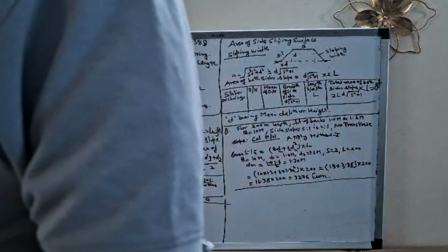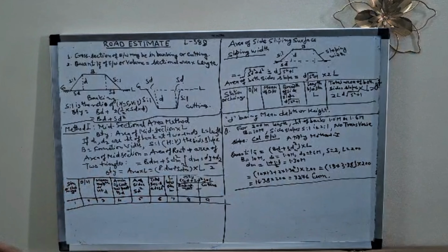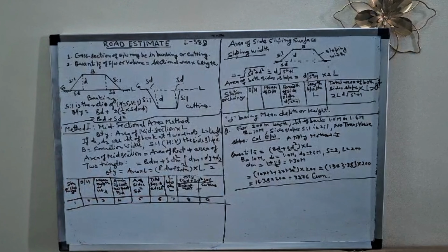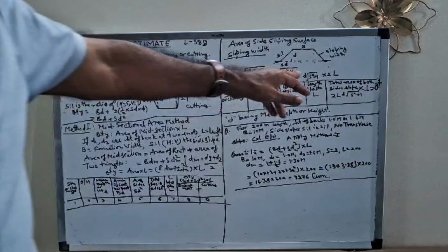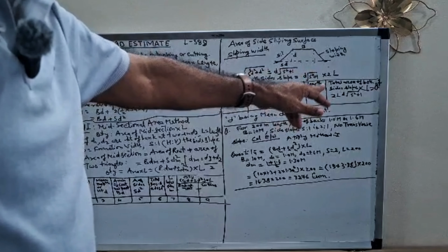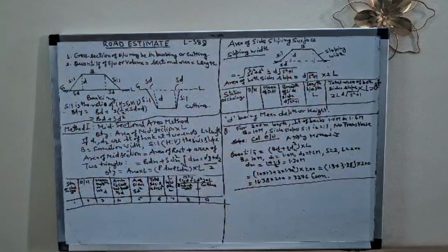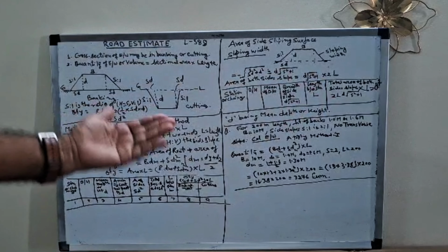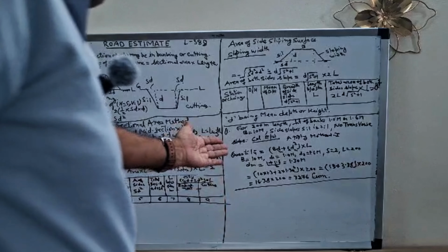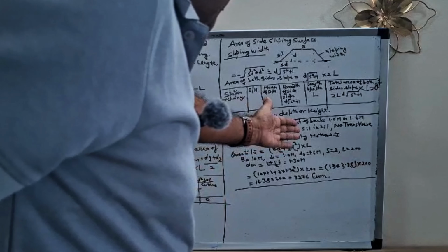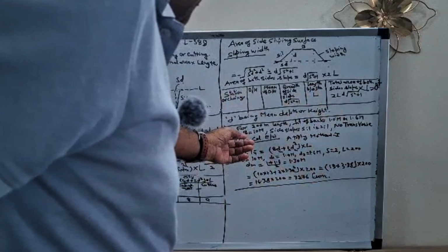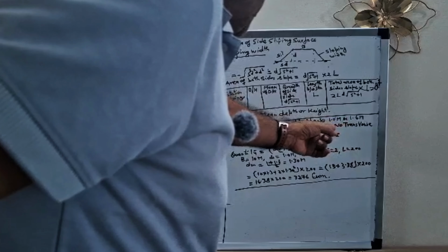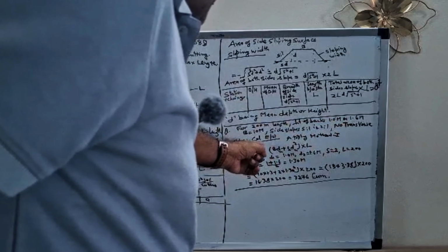So D being the mean depth, you can always calculate the earthwork quantity, and for the pitching work on the sides you can have the total quantity of sloping surface area. Let us take an example: for a 200 meter length, the heights of banks are 1 and 1.6 meter, B is the formation width, the side slope is 2 to 1, no transverse slope. Then calculate the earthwork.